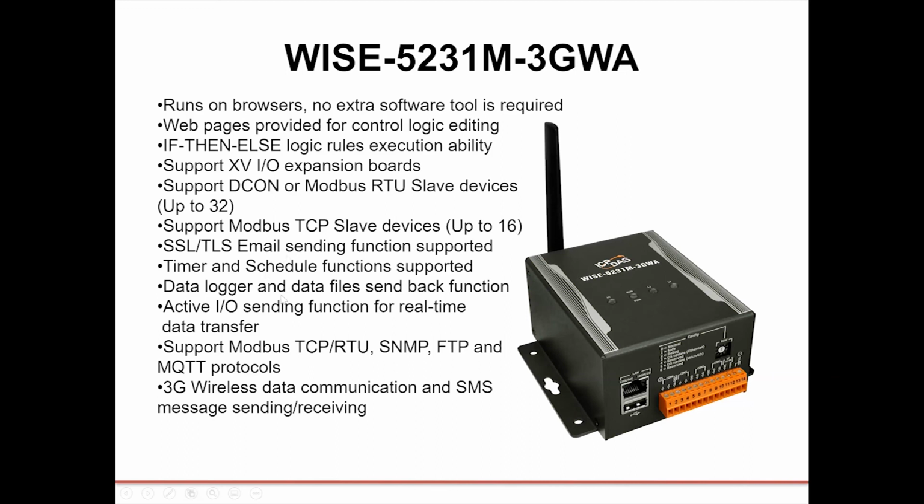And of course, in addition to scheduling data send, you can use it for real-time data transfer. It supports Modbus TCP and RTU, SNMP, FTP, and MQTT protocols. And of course, this is the 3G version, so 3G wireless data communication and SMS message sending and receiving is supported.